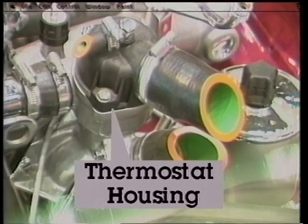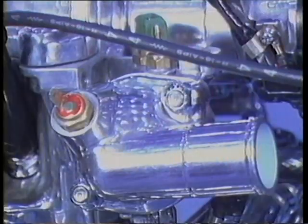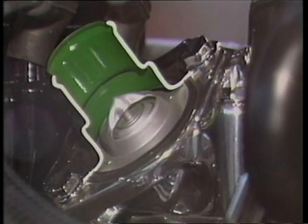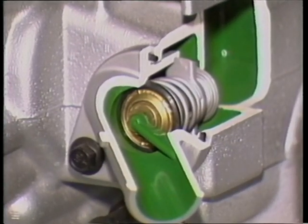The thermostat housing is an enclosure for the thermostat. It can also provide metal fittings for various hoses and threaded holes for sensors. The coolant temperature sensor can thread into the side of the thermostat housing. The thermostat and its housing are often located at the top of the cylinder head, like this one. However, the thermostat can also be mounted in the side of the cylinder block.